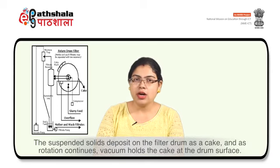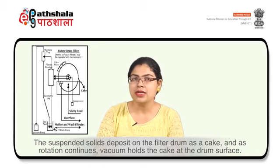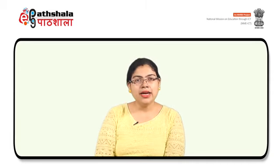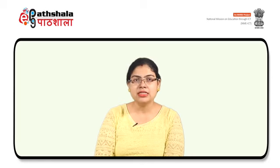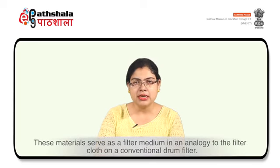The suspended solids deposit on the filter drum as a cake, and as rotation continues, the vacuum holds the cake at the drum surface. For solids that tend to block the filter cloth, a pre-coat of filter aid such as diatomaceous earth, perlite and cellulose is deposited on the drum prior to the filtration process. These materials serve as a filter medium in analogy to the filter cloth on a conventional drum filter.